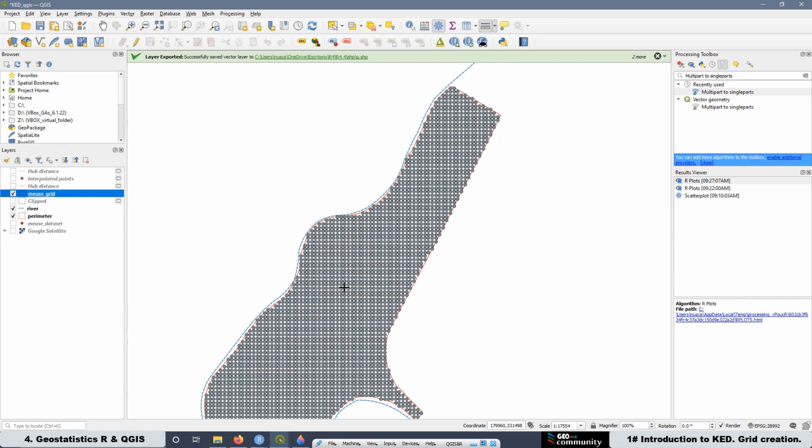It's very straightforward. The last thing that we are going to do today is to convert this vector layer to a raster file. To do that one, we are going to use a different script. Let me copy this one. It's just a rasterize. Then it is this option over here, rasterize vector to raster. Then double click.